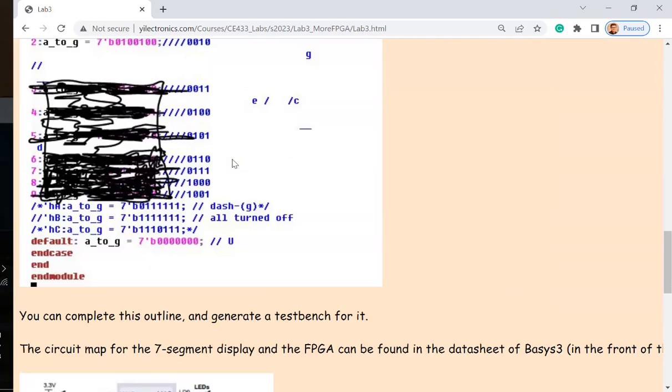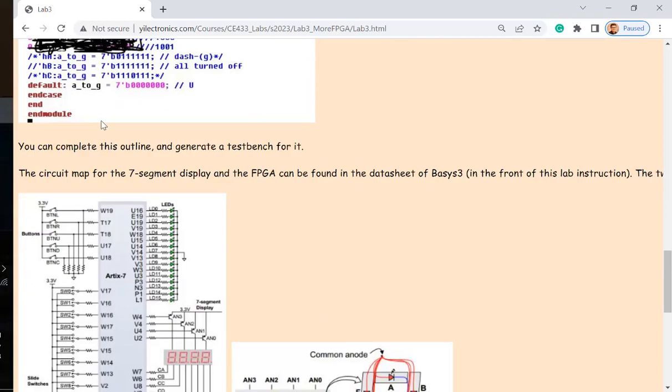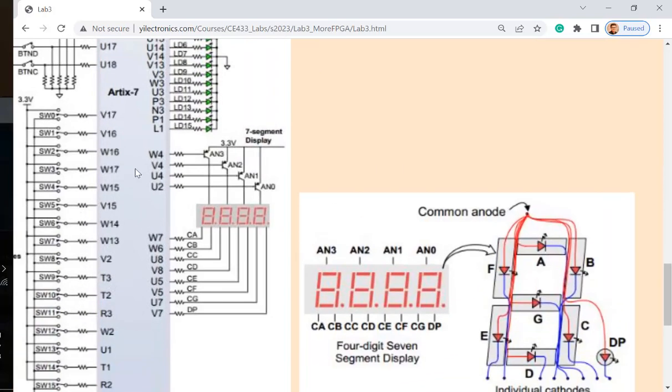And now this is part of the code, right? So at the very beginning, you should know that these are all physical pins. So in your constraint file for the FPGA, there will be keywords that you can use. Like for the switches it's SW, for LEDs just LED, and for the 7-segment display I think it's SEG, which are these, right? 7 or 8 bits.